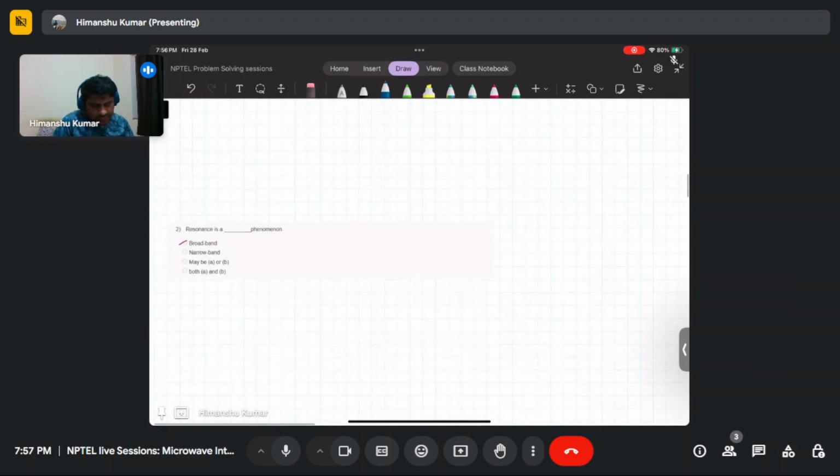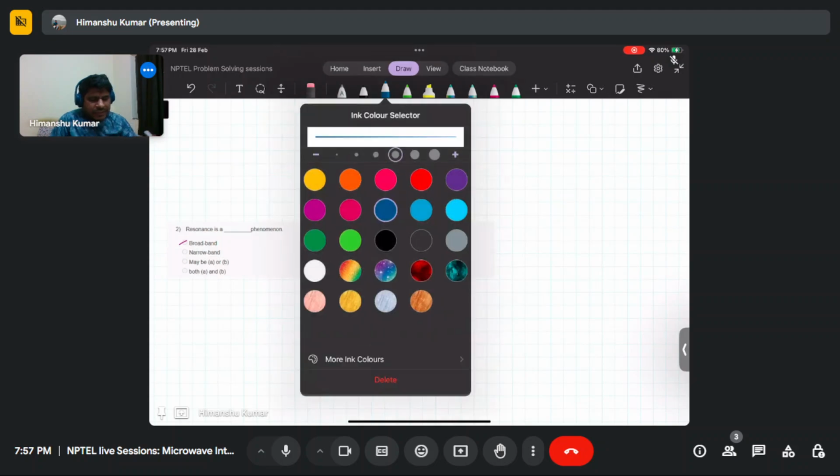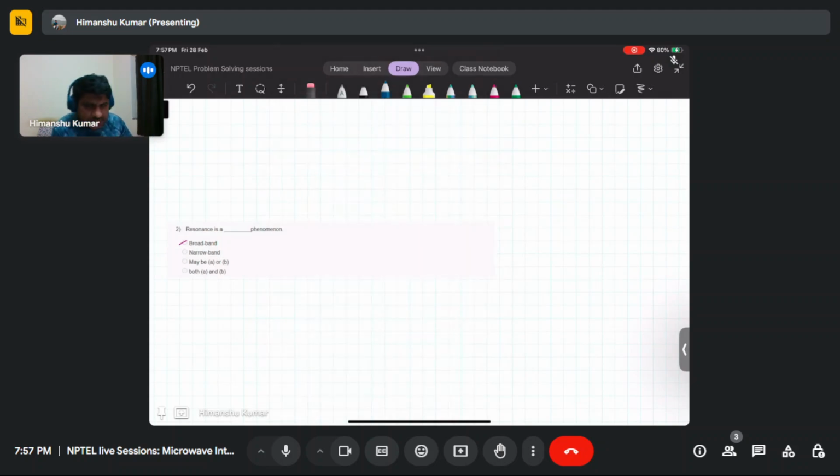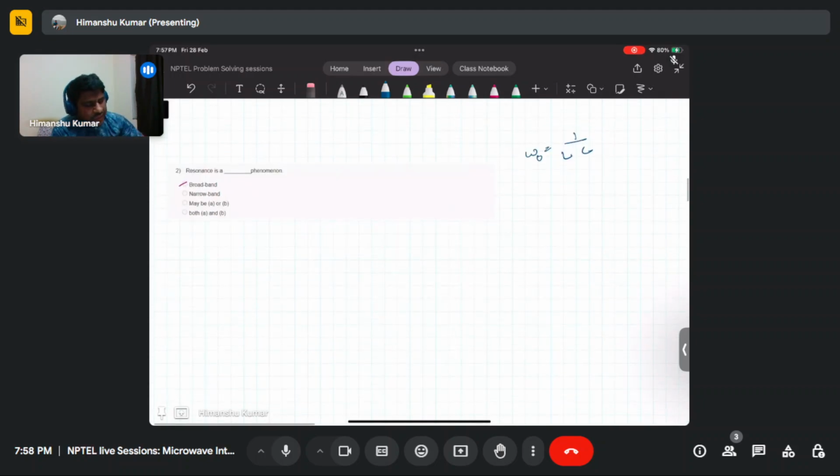Resonance is a narrowband phenomenon, because if you consider the LC equivalent, the resonance condition occurs for only one combination of L and C. So if you have some circuit, only very near that narrow band of frequency it will pass, or it will have this kind of response.